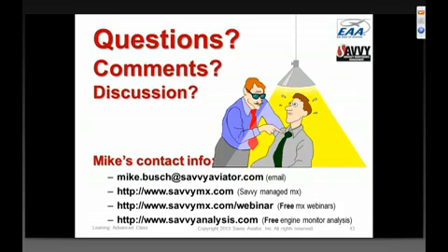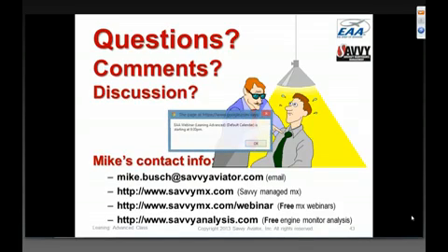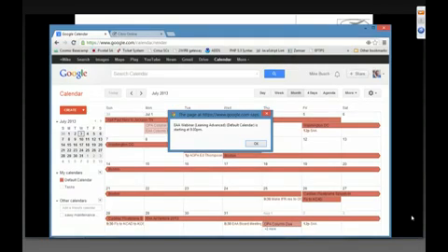If you have a digital engine monitor that gives a digital readout, one thing you can do is, before you start the engine, look at the cylinder head temperature digital readouts. They should all agree, and they should all be at approximately ambient outside air temperature. You can't do that with a regular analog CHT gauge, because normally it's on the peg until the cylinder head temperatures warm up. But with a digital gauge, you normally can read that temperature when the engine isn't running. Before you start the engine, all cylinder heads should be at ambient temperature, so that's an easy way to do a quick check on the accuracy of the system.